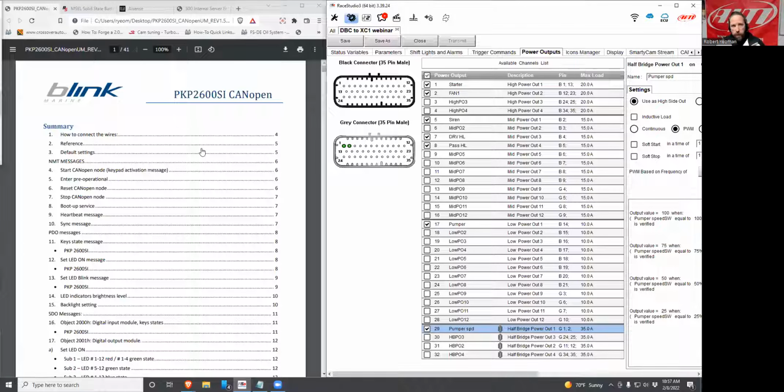Yes, there is. What you're going to run into is multiple PIDs. If you want to send 2 messages, there's no timing structure in CAN output for you to hold a message until you receive the answer from your previous message. So if you want 1 PID, sure, it's not a problem. You could send the request to the request ID and process the information on the way back. But I can't put in an if statement that says only send this message if we've received a confirmation of the previous message. Okay. So it's there, but it's fairly basic.